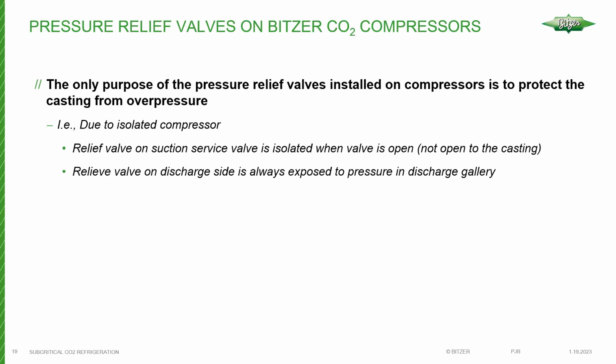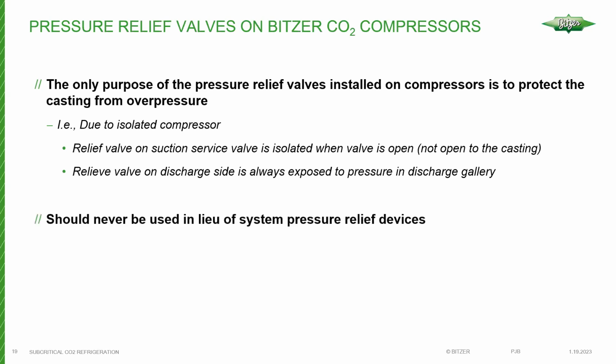And on the transcritical side, that relief valve is always exposed to the discharge gallery just upstream of that. So this is after your cylinders and the valve plates. The discharge gallery, that area inside the compressor, can vent through this relief valve in the event of an overpressure situation.